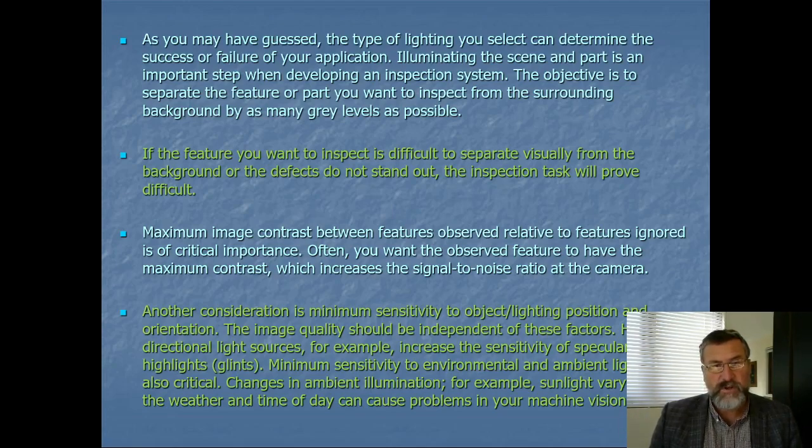Well, there's a number of ways of doing it, but one way of doing it is to have diffuse illumination. So companies like Stemmer, they sell lights which have various constructions of LEDs, like a ring light is a favorite. You have a ring of LEDs and a hole in the middle, and the image is taken with the camera through the hole in the middle. But you've got this diffuse illumination, so it's not directional, and you're going to be able to minimize the highlighting in that way.